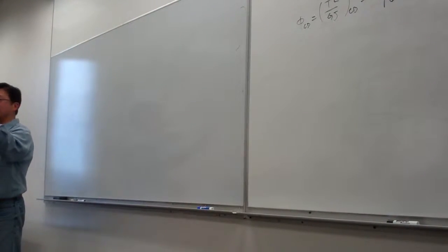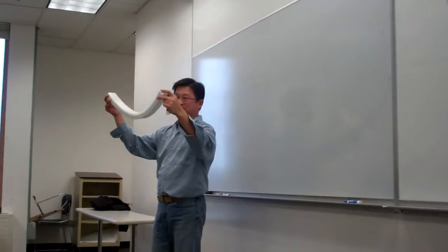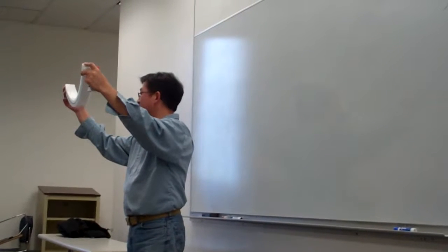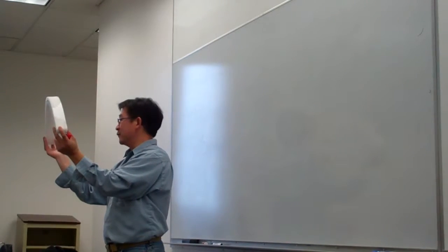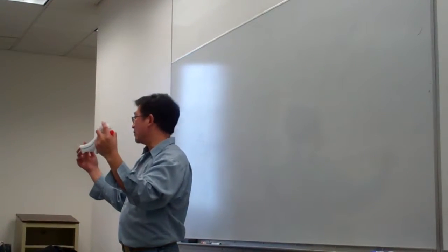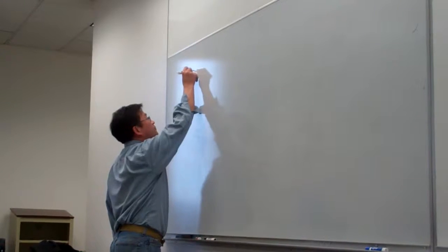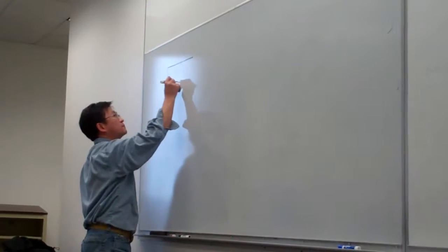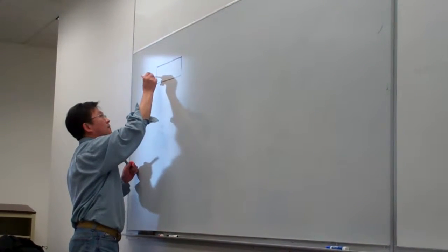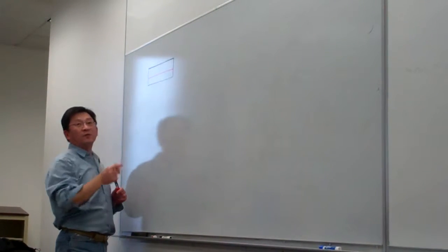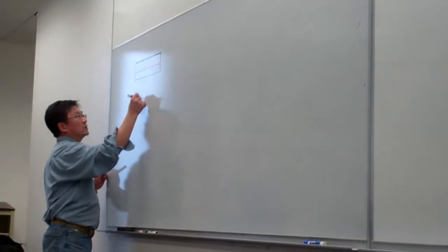So basically here I make a line. The upper portion above the line is in compression, and the lower portion below the line is in tension, or the opposite, vice versa, like this. Based upon this, last time we came up with this. And there exists a certain fiber. This fiber won't change in length, won't deform before and after bending.